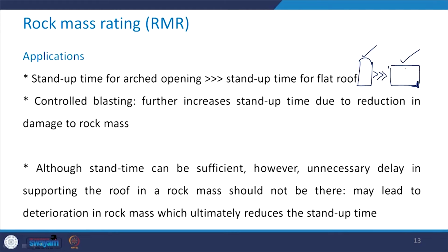Although you have sufficient stand up time, unnecessarily we should not wait till the end of that time in order to provide the support system in the rock mass. Although the rock mass can withstand up to that much stand up time, wherever there is a free surface, stress release occurs and there will always be deterioration in the rock mass, which will ultimately reduce the stand up time.